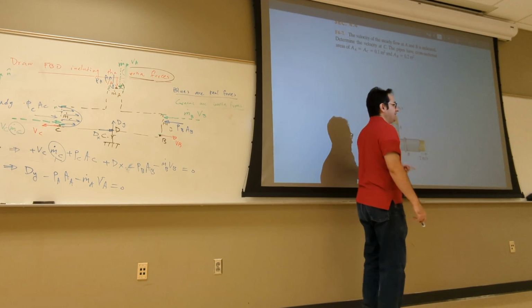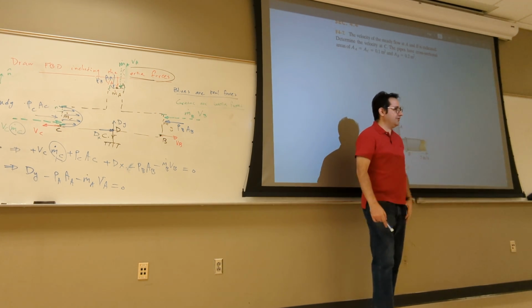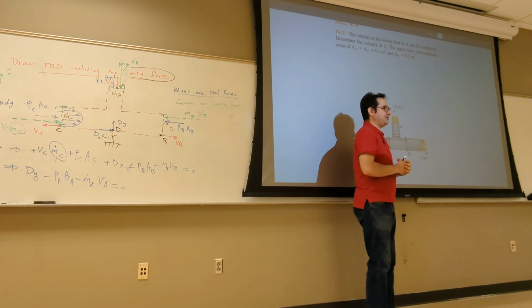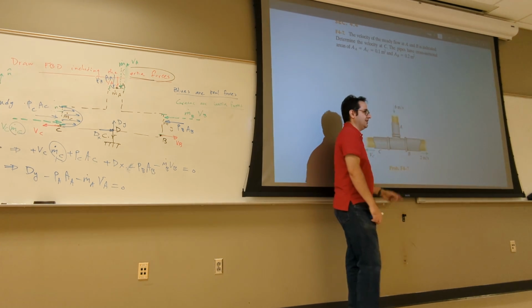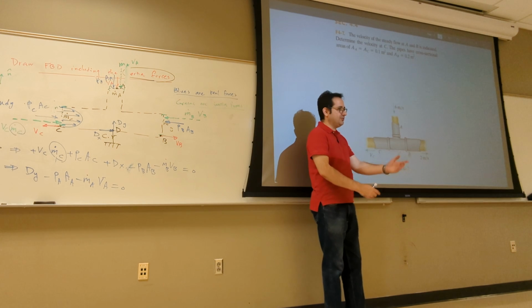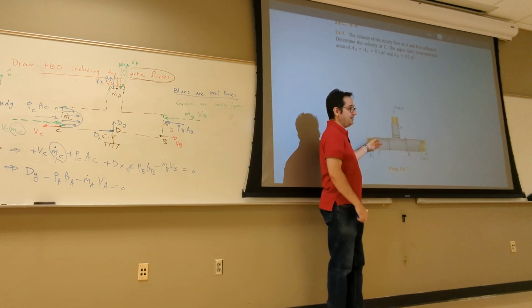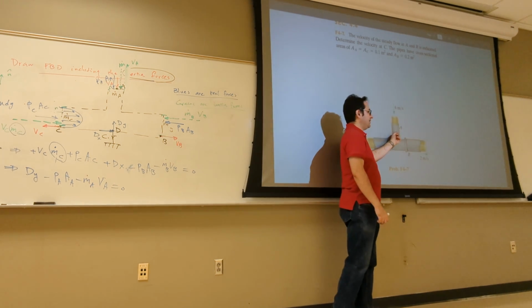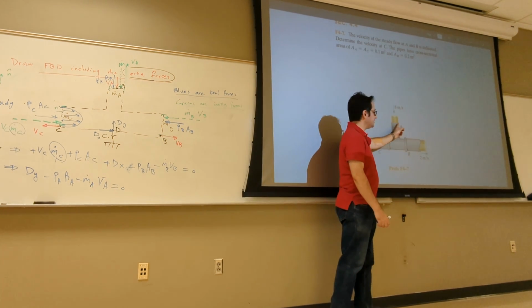And then the pressure at A, let's say I give you pressure here and don't give you pressure A. Then what do you do? You just put unknown pressure A. You can, and you get good partial credit, very good partial, but you don't get 100 out of 100 for that question. If you want to get 100 out of 100, what do you do? I don't give pressure here, I give pressure here. Bernoulli equation. You write the Bernoulli between the streamline. If the areas are the same, I may give different areas. If the areas are the same, I'm sorry, velocities, and this height is small. But if this height is like 10 meters, then you have to put it there. Then you find pressure at A.